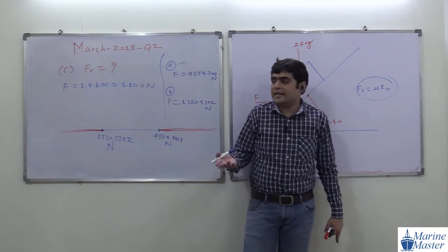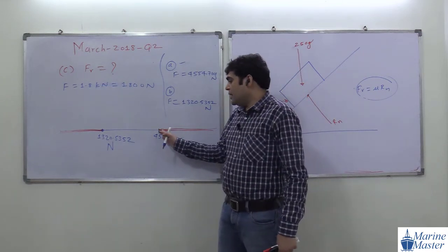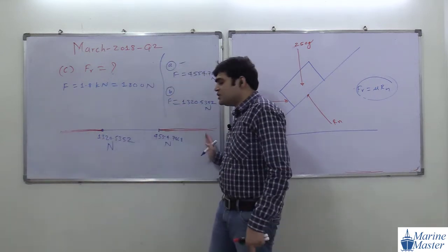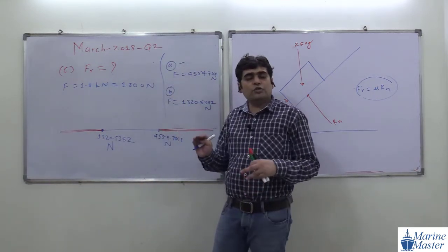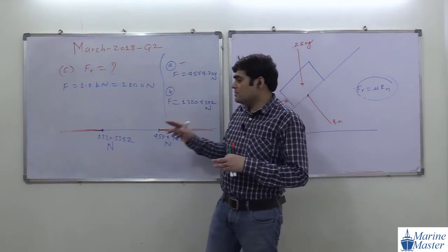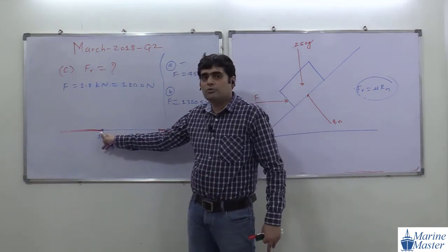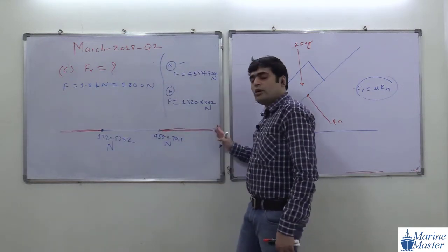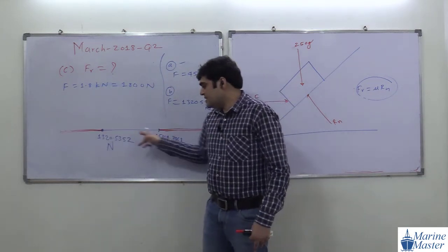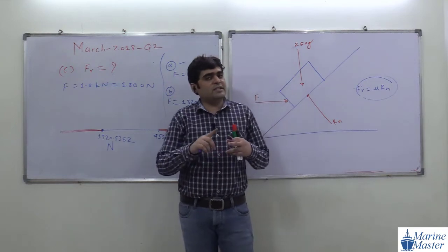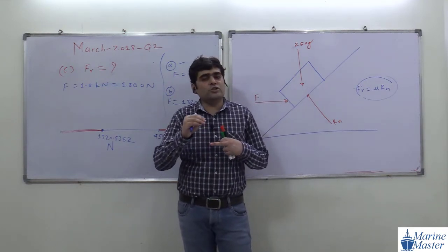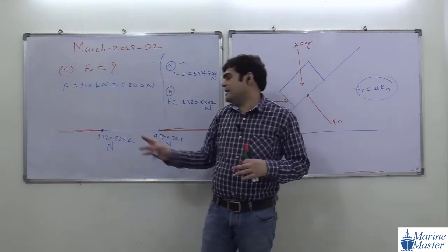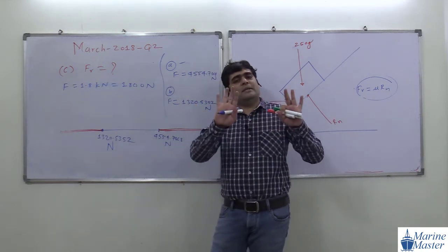No, we can't use that relation, because we can use this relation in this region or in this region, since in both regions the object's motion is just about to start at this point, or it is moving here. Here also the object is moving. But in this scenario, the object is neither in motion nor is its motion about to start. It remains whatever it is, whatever force we apply in this region, so the object stays as it is.